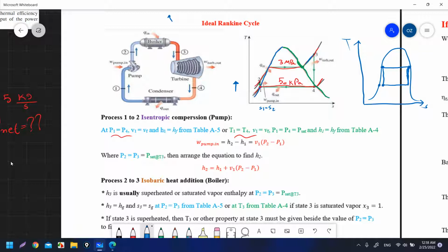Okay, that is why always in the Rankine cycle you will find that state 1 is at the saturation liquid line, and if it is not like this, if it is not at the saturation liquid line, he will give you a sentence that will clarify where point 1 is, because sometimes they subcool the state to be here. Okay, why do they subcool the state?